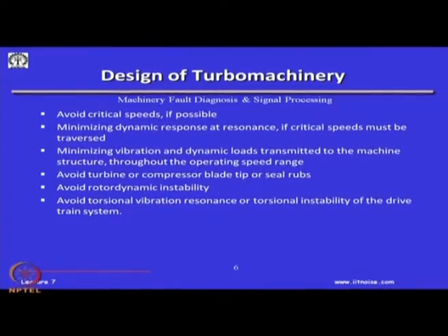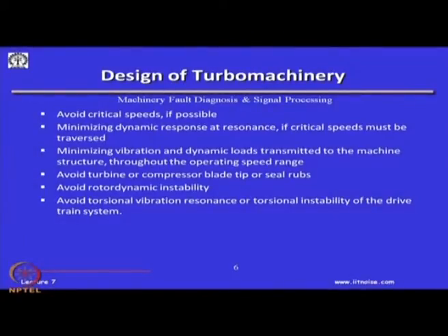We can talk of an aircraft engine, a steam turbine, even a large set of pumps, but these have to be taken into account. Some of them are vertical. If you go to many of the power plants, particularly the hydel power plants, you will see a lot of vertical machines, maybe the Kaplan turbine, etc. In vertical turbines, the shafts are not horizontal but vertical. We have the effect of the gravity loads on the bearings. How do you select the bearings, the thrust bearings, the pivot bearings, the pad bearings, etc.? So, turbo machinery from a dynamics point of view is a very complex thing. As a designer, people do take care of it, but our goal in this class is how we maintain and monitor the health of such large, complex turbo machineries.